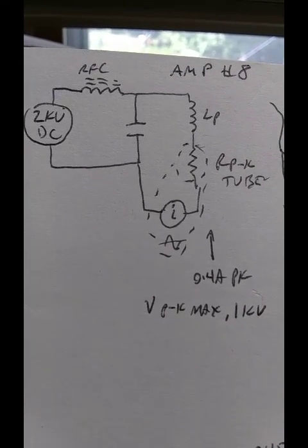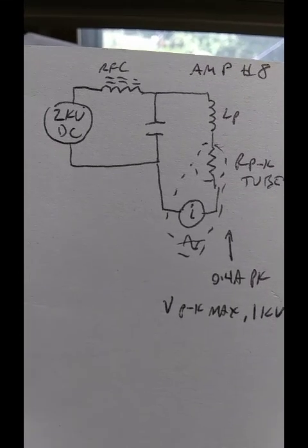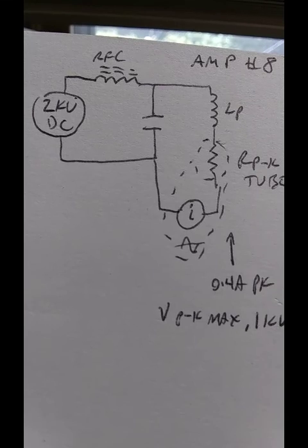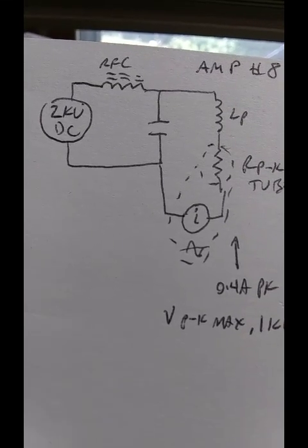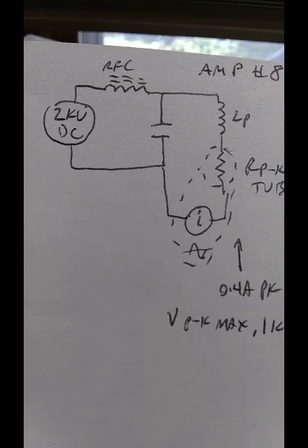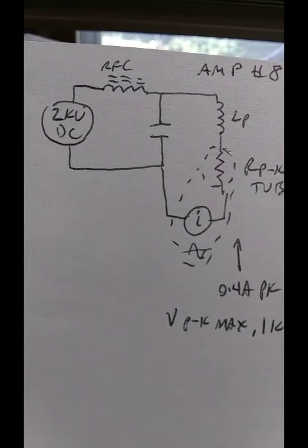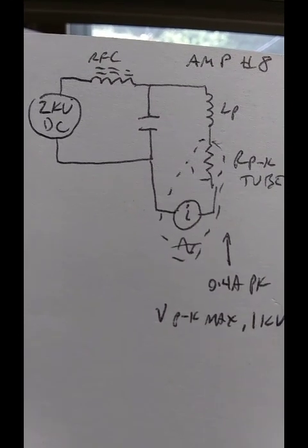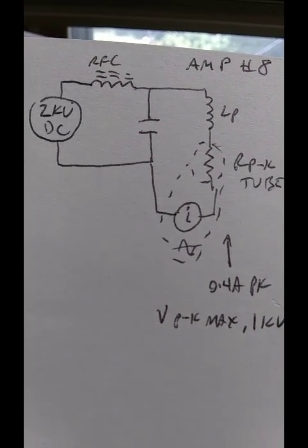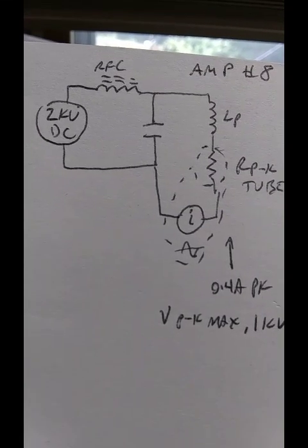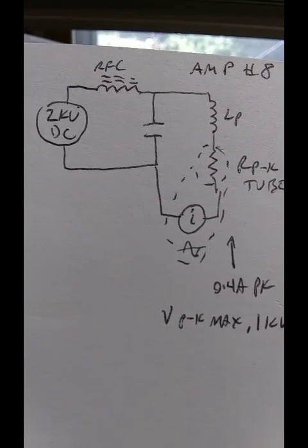That field has become a voltage source. If we try to cut that inductor lead from the circuit, there will be a very bright white arc where the inductor voltage has suddenly skyrocketed in a desperate attempt to maintain the same current flow. If you've worked with inductors and switches, you know that voltages can be extremely high, tens or hundreds of times, if the switching rate's fast enough.